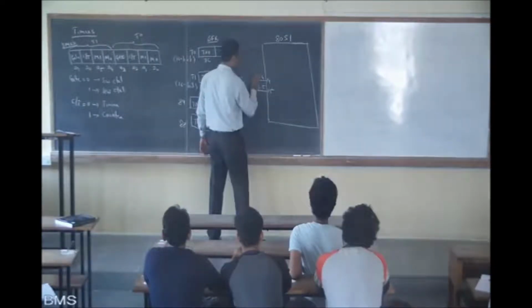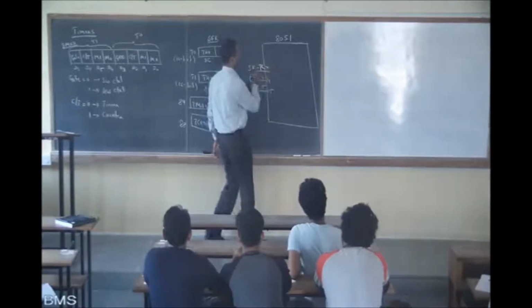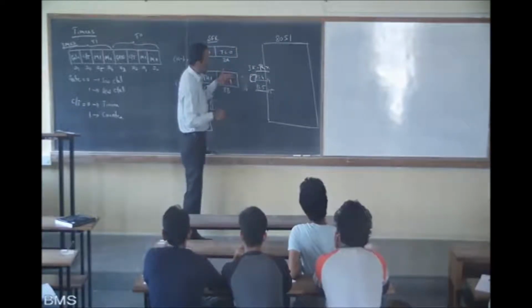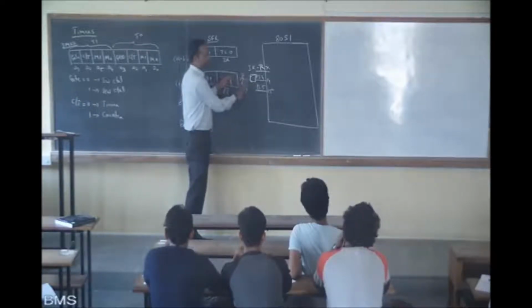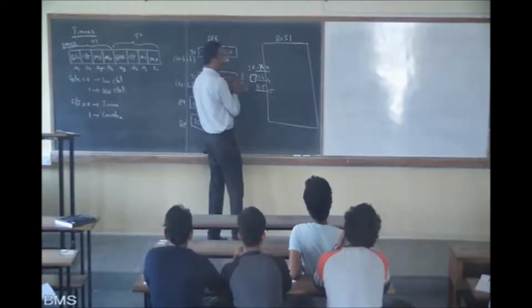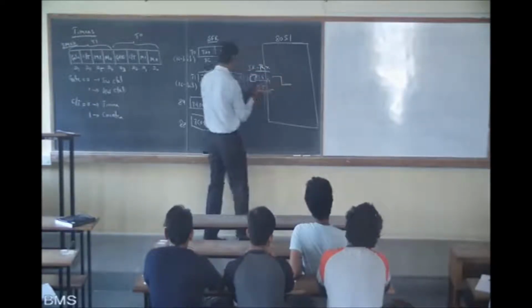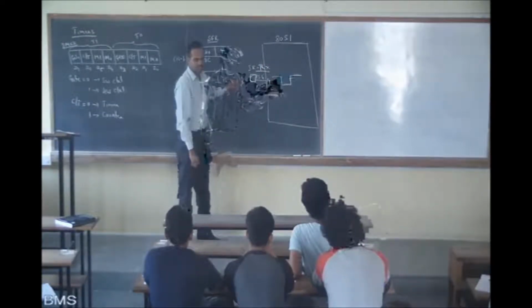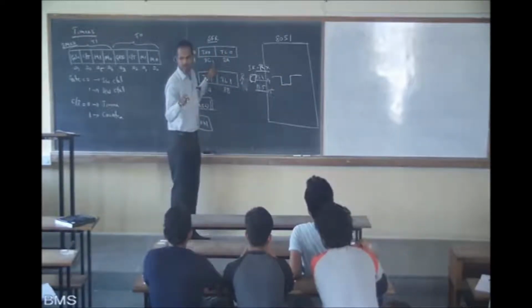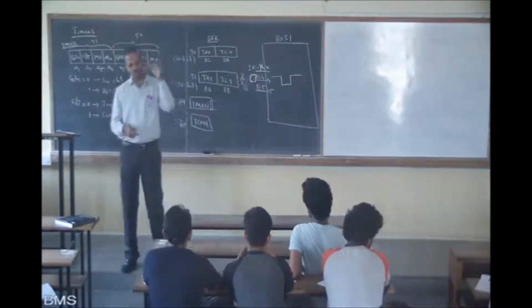P3.4 will connect one IR receiver. On the other side, we are emitting the IR, so we connect the IR emitter. When there is continuous connection between these, there is no pulse generated. When somebody comes in between, the signal going from here to here will be cut. That means when there is nobody, it is high. When somebody comes here, it will go down, and then when he passes, it goes back. Is this clear? So if this pulse is given to the counter clock signal, then it acts as a counter. Did you get this? Both are counters.